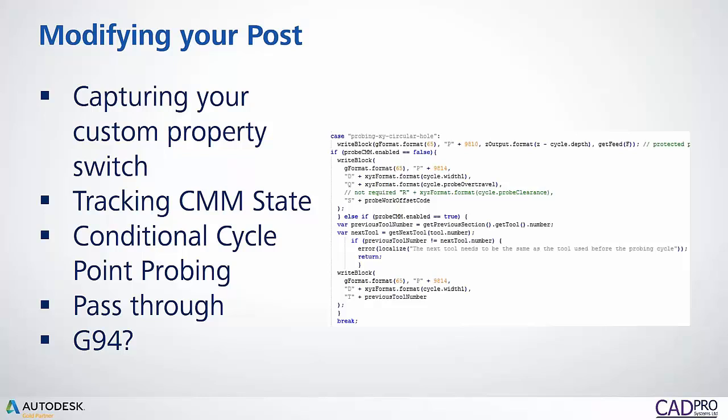Man, this happened on 2 different machines now. The probing macro in the Haas control. That means it ends up in some other feed mode, so you have to switch back to feed per minute after you run the cycle.